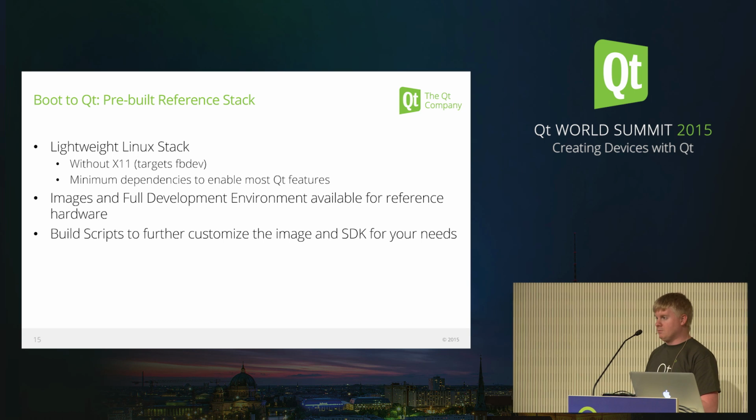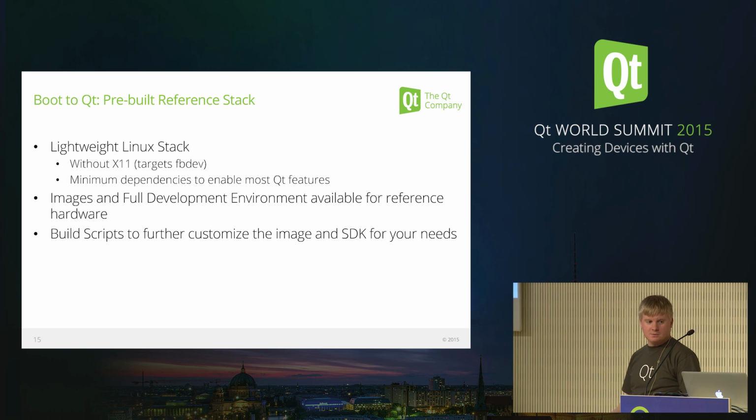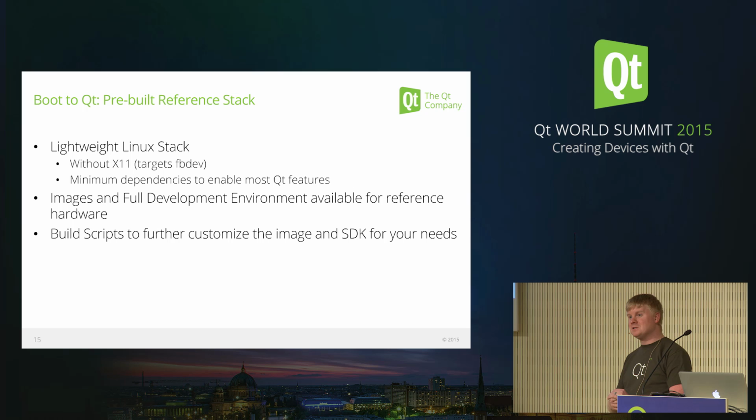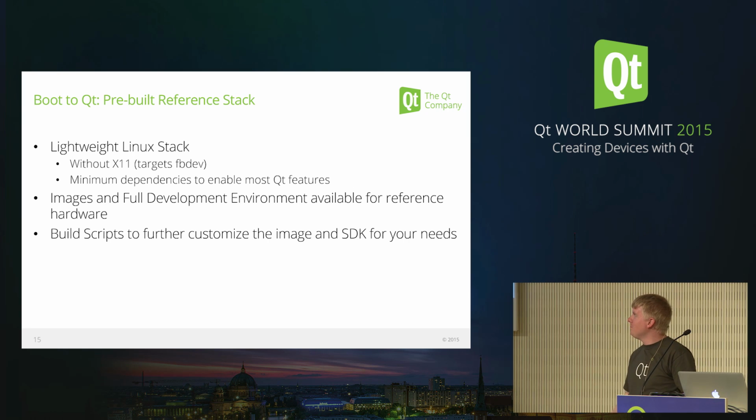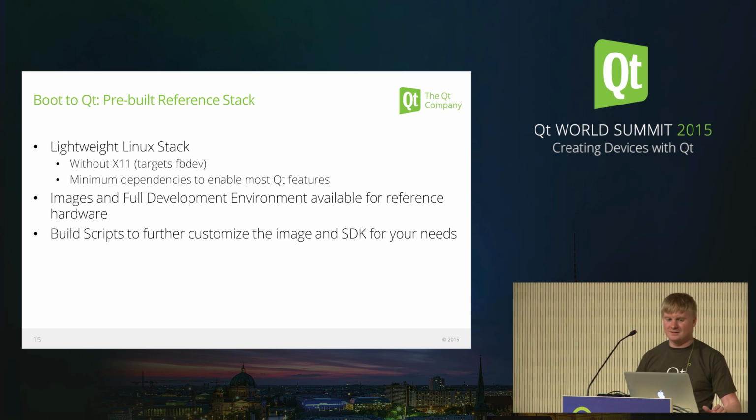And we're not using X11, it's a bit heavy for the embedded devices, and we want to be able to use OpenGL, so we're using the OpenGL ES EGL full screen plugin. And that interacts directly with fbdev in most cases.